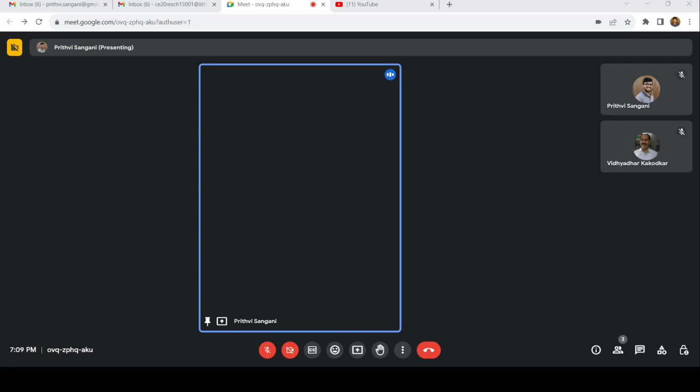676.8 by AE. So this is minus. Okay, this is minus. What does the minus sign mean? The minus sign means the displacement is opposite to the applied force, so actually the displacement is in this direction. The delta 1, which we assumed to the right, is actually moving towards the right side. The joint C is actually moving towards the right.